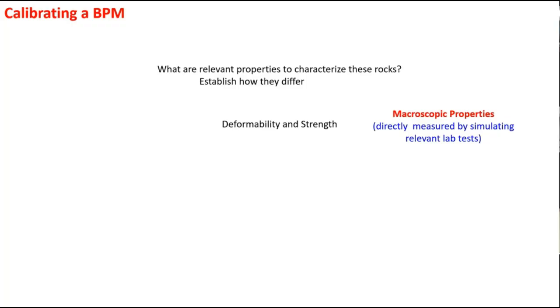We could take that rock and put it in a direct shear machine and slide the top and bottom surfaces in different directions and force a fracture to form along it. And that could be the point at which that happens. It's going to be an abrupt thing. It's going to load, load, load, and then crack. It's going to break apart. We could call that a strength, right?